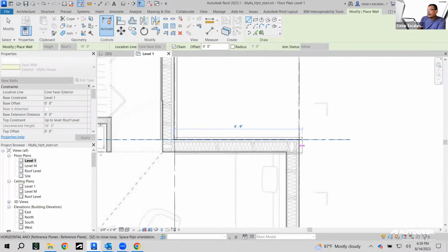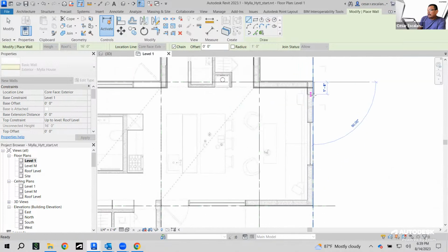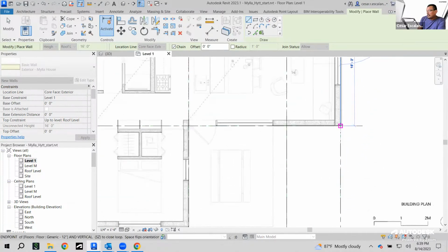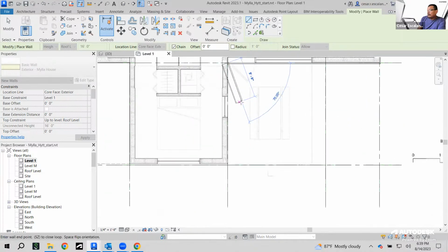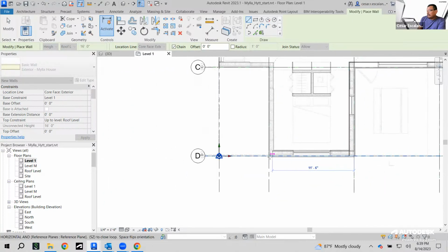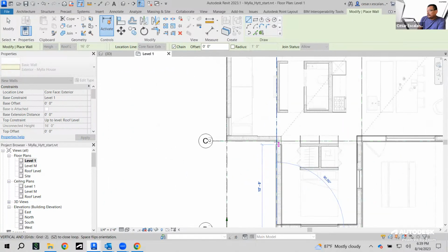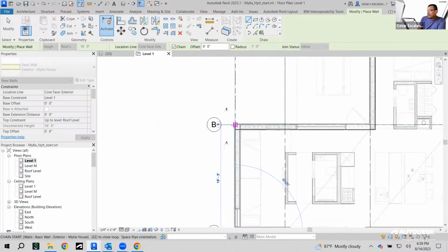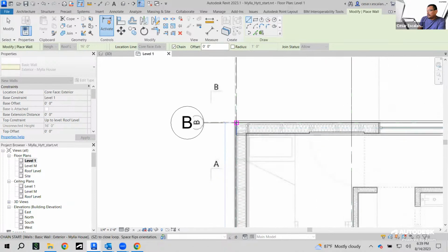You don't have to fillet them manually. The height of these partitions is 16 feet. The exterior core of the partition is aligned to the edge of the slab, because the next exercise is to lower that layer by 4 inches.